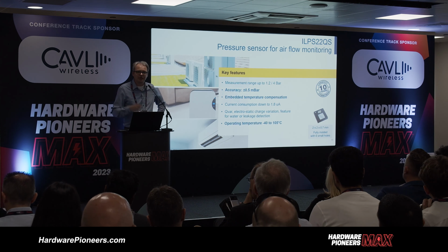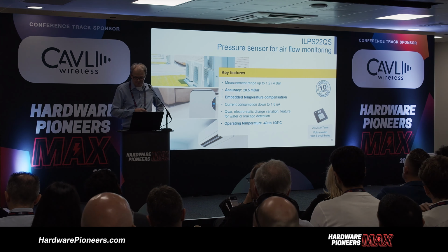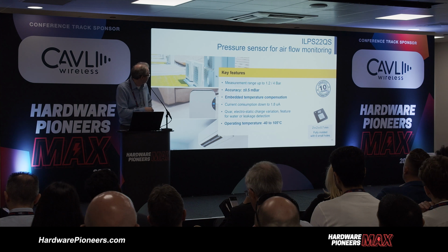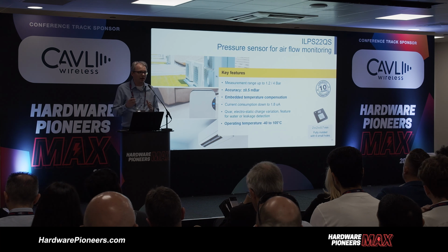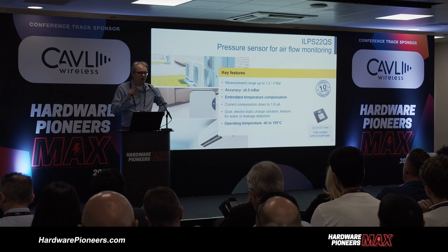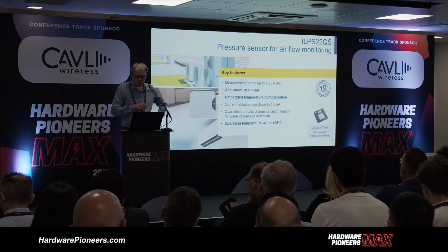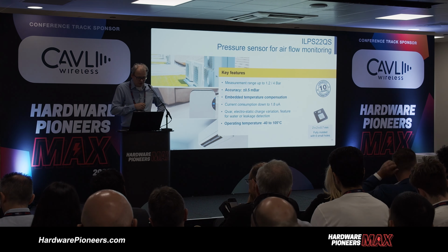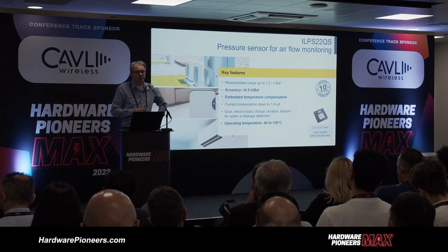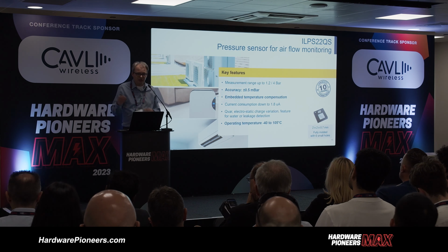But then, if it's somehow related to airflow, in this case it makes sense to use pressure sensors specifically. This component would be a perfect match for different kinds of HVAC systems, and basically anything with air filters, where you can start to see when the filter is getting clogged. This is one type of condition monitoring of machines, and you can use either 1 or 2 of these sensors to make this type of measurement. Just as background, this type of component is also used, for example, in vacuum cleaners to see when the bag is getting full.